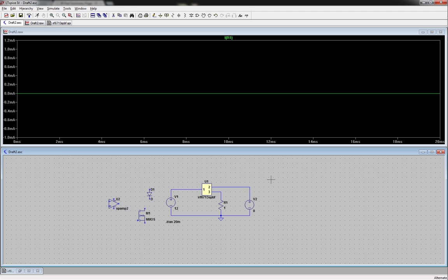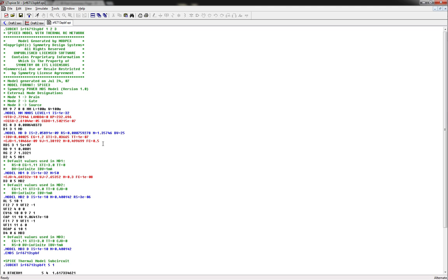Sometimes I can't cover everything in a video, like all the manufacturers' sites, because different manufacturers have different ways of doing things. Some of those files you'll download, they'll say that it's a SPICE file, and it'll be a .lib file, and it looks like it's got 15 or 20 different subcircuits in it, and that's fine too. What you would do in that case is pick the one that's yours, because a lot of times, especially with FETs, they'll lump a whole family of FETs together, with multiple subcircuits in one file, just tons of them.